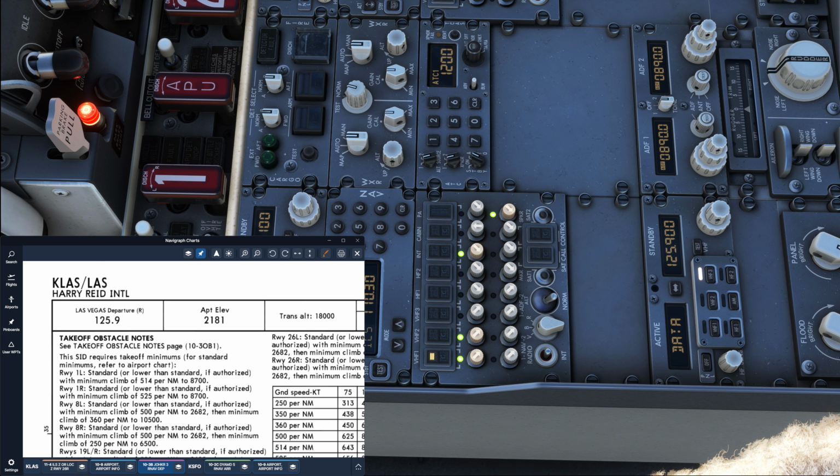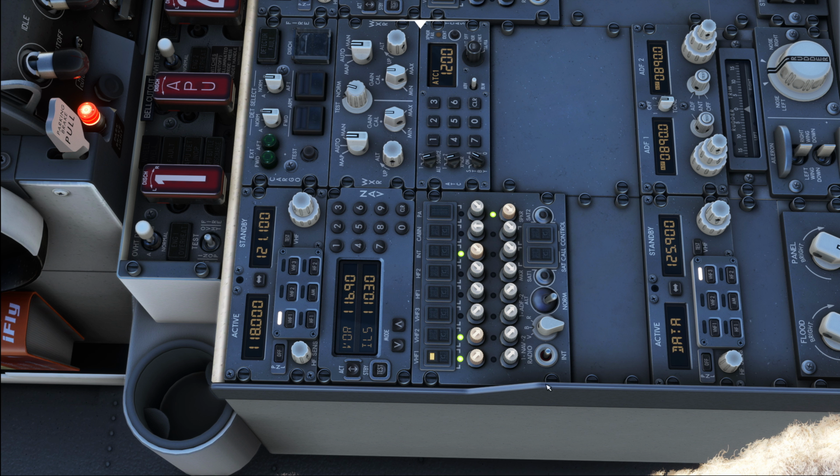so that when we do our lineup on the runway, once we have been transferred to the tower frequency, we can simply look down here, take that frequency and dial it up in the standby of the active radio, so that once we have tuned tower, we are ready to simply switch over to departure as soon as we get the handoff. Quite a nice shortcut that a friend from the 777 has showed me, but works very well, so I can only recommend you to do this as well.